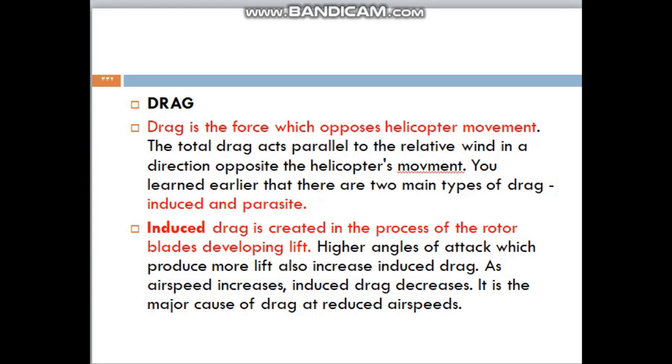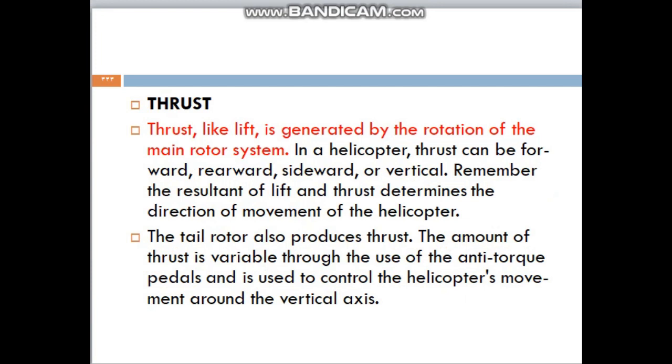The induced drag is created in the process of the rotor blades developing lift. A higher angle of attack, which produces more lift, also increases induced drag. As airspeed increases, induced drag decreases. It is the least major cause of drag at reduced airspeed.